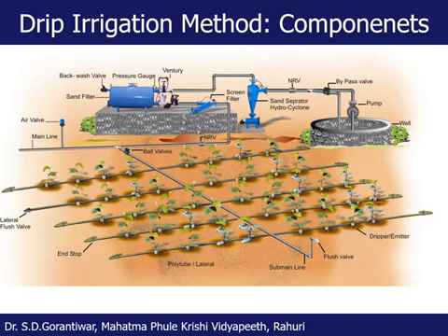And if this entire water load flows back up to the pump, then this water will fall over the impeller of the pump at great pressure, and the pump impeller will be damaged. So in order to protect the pump, basically the pump impeller, from the returning water in case the pump is stopped, a non-return valve is necessary.